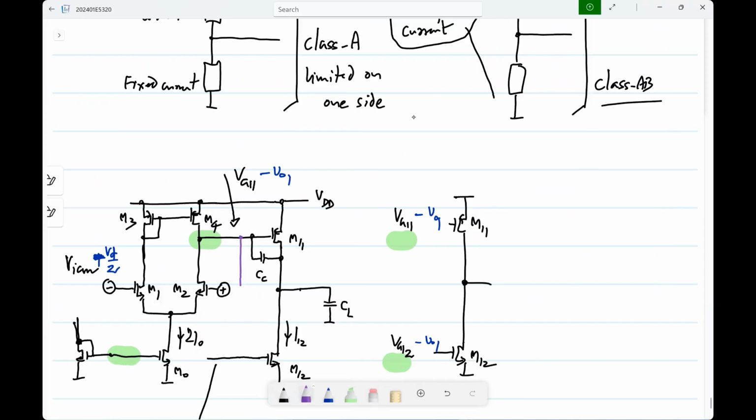You just connect these two, right? So you can do that, but what is the disadvantage of that? No, they are the same. That is okay. But what is it? One is, of course, now because these two are the same, you have a compromised swing limit as well. Now with very low supply voltages, that may be okay because anyway you are not getting very high swings. That is one problem. What if you connect it up like this?